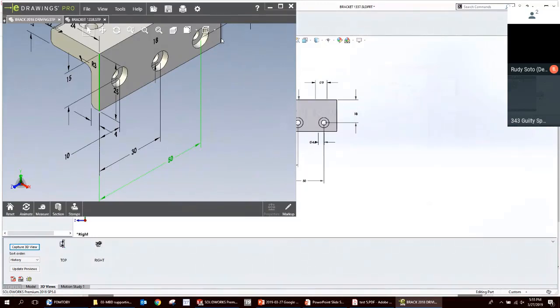Yeah, because you could do like 80% of your work right up front in the model, and then just add a few other dimensions and tolerances. That was the cool thing about annotation views. When I did that webinar for that company, it was probably a couple of years where I was using those annotation views a lot because I was setting myself up for drawings. Then when I make a drawing, it was just like everything landed right where I wanted it. It was good to go. Supported section views, so you could really do a lot with that in the model. And then also, if you ever want to recreate the drawing, or if you lose the drawing, like the drawing is corrupted or anything, everything's in the part file. So it was really nice. So yeah, I totally get where you're coming from on that. And I'll find out for you if that will actually carry through to the downstream stuff.